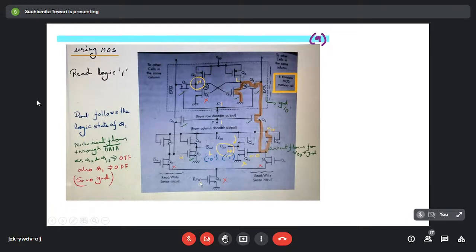As soon as we are making this input 0, it will simply switch off this transistor. This Q17 won't be conducting now. If Q17 stopped conducting, then automatically this transistor and this transistor won't conduct, because through this path it is not able to connect with the ground. So these two transistors will be switched off, meaning whatever the value in here, regardless of that, it won't be able to conduct or send the signal to ground. So these two are effectively off.